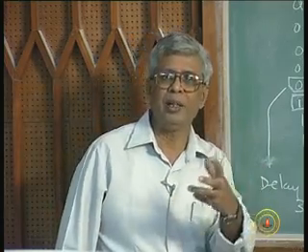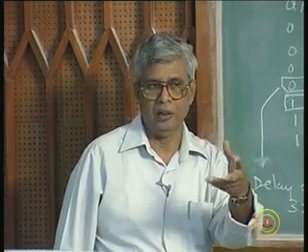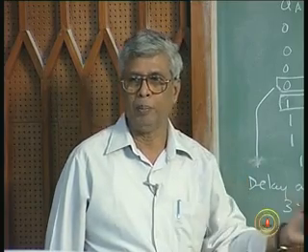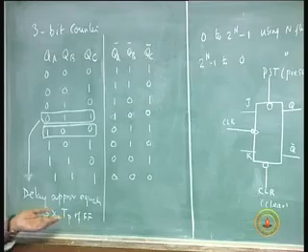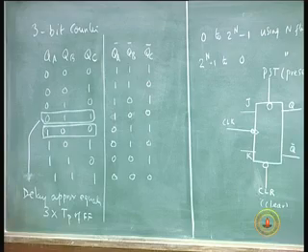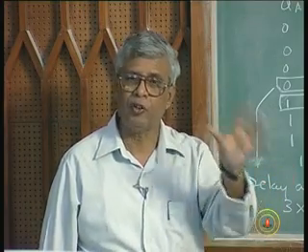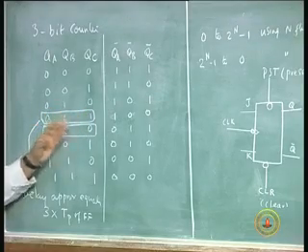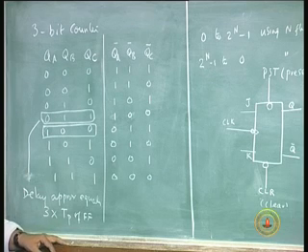See, once you have a number, you can always compute, but you should know there is a concept here. You should know there is a number you have to look for. Once the number is given to you, I can make it approximately 2 nanoseconds, but later on you find from the data sheet it is not 2 nanoseconds, it is 3 nanoseconds, that is all right. You have to do a computation, but you should know there is something like that we have to take into account. So there is a delay in each flip flop stage which affects the change, and the more flip flops there are, the delay in counting becomes longer and longer, right.